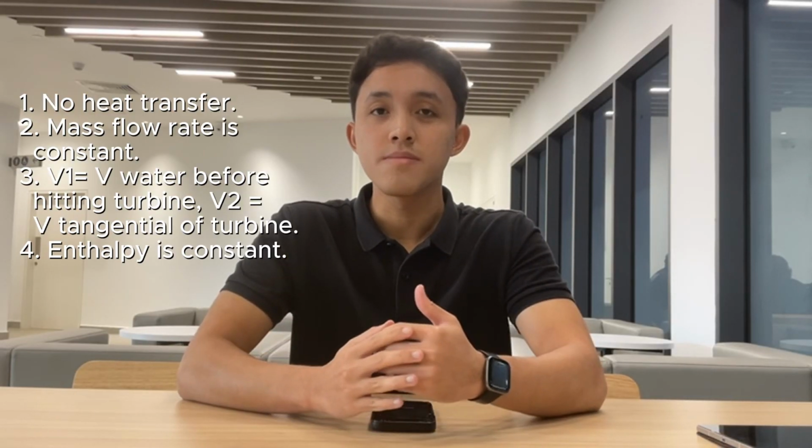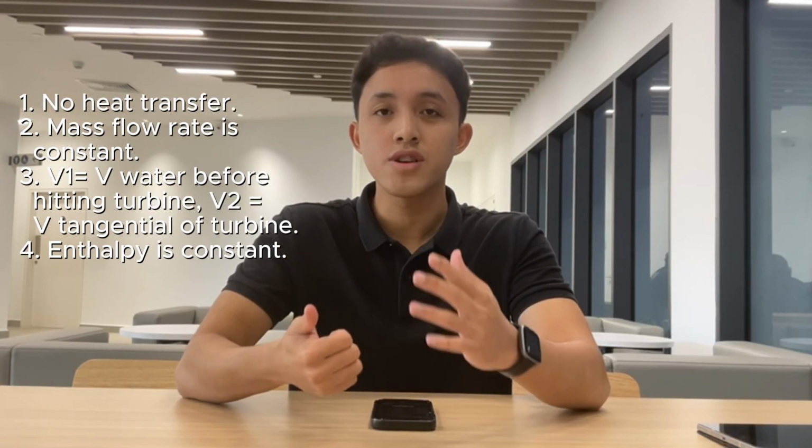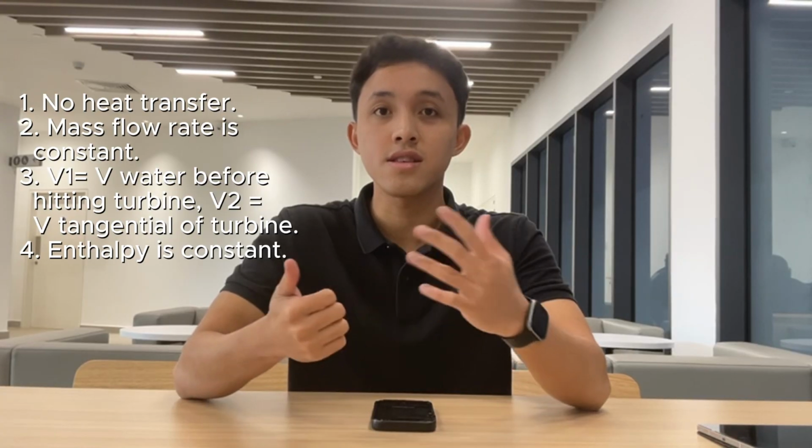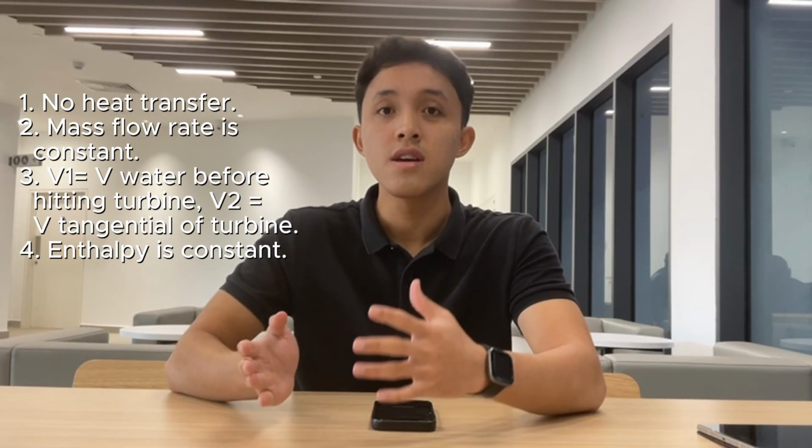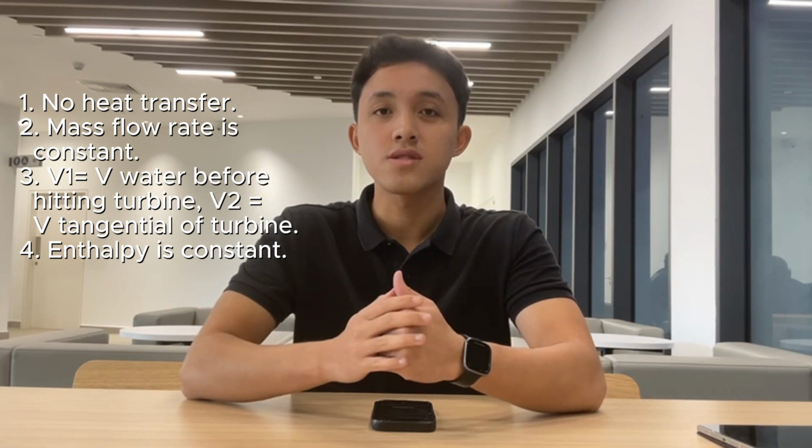Why are we assuming this? Because we are assuming that the pressure between the first and second state is equal, which is equal to the atmospheric pressure, since the water is exposed to the atmosphere, and also that the temperature remains constant throughout the process.